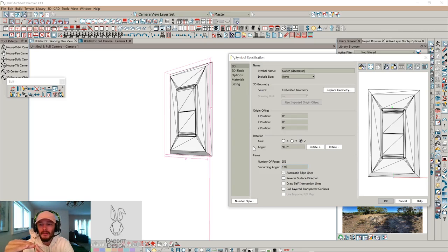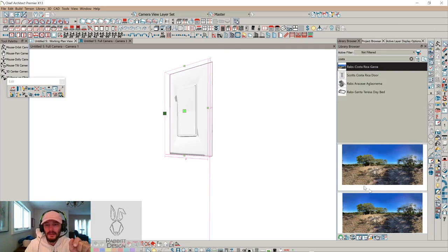If the polar degree of one face when compared to the next is greater than 90 degrees, now it will be considered part of one face because I've specified that our smoothing angle is over 90 degrees, meaning the return from the face of this rocker back is going to be connected because we've got a connected edge there. You'll see what I mean in just a second here. And you can see we've got some funniness in the cover plate, but that doesn't matter.